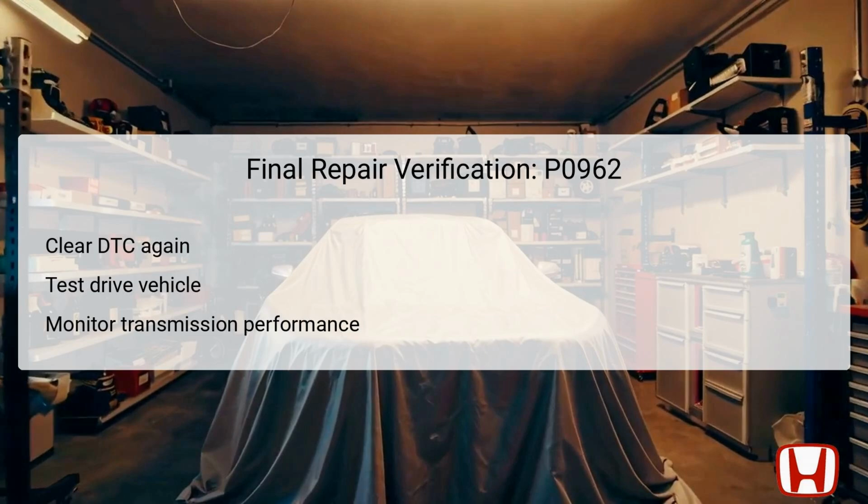After completing the repairs associated with DTC P0962, it is crucial to verify the effectiveness of the conducted fixes. This starts with clearing the DTC once more using the HDS, resetting the vehicle's diagnostic system. Following this, a test drive is essential to assess how the vehicle behaves under normal operating conditions. During the test drive, attention should be paid to the overall performance of the transmission.